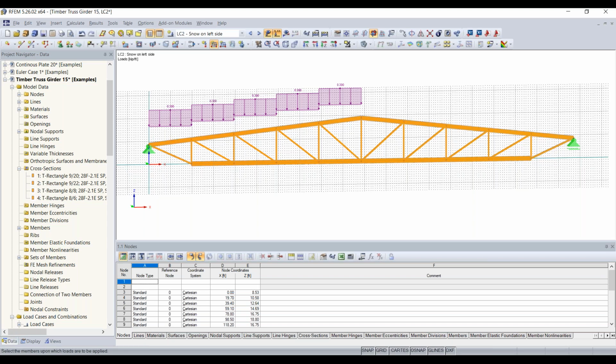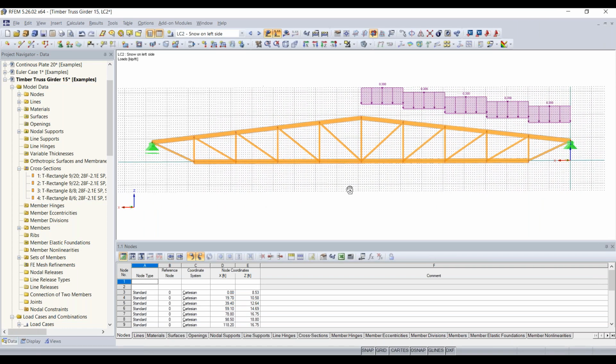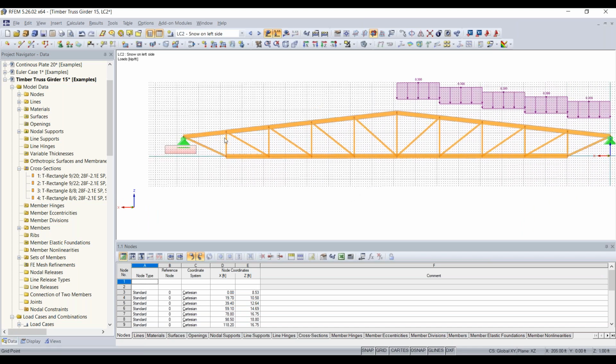And you can see that it's the projected member length of that, taking into account how snow will act on our roof there. So we'll right click, and now we would just want to do the same thing for the other side. So I'm just going to rotate my model, and then I can just highlight again, selecting only the beams up here. And then I can choose new member load.